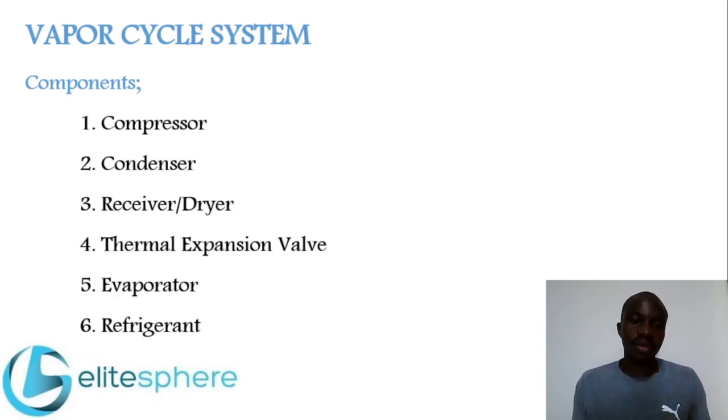From the compressor, this compressed and high pressure gas flows to the condenser. Ram air that passes across the condenser cools this high pressure gas, and by cooling it, it condenses the gas to liquid. So in the condenser, condensation of the high pressure gas takes place, and what comes out of the condenser is a high pressure liquid.